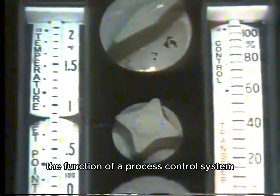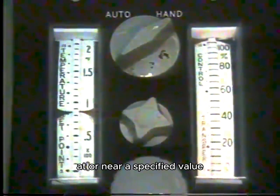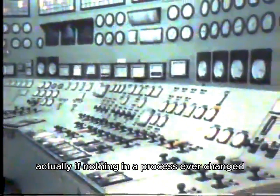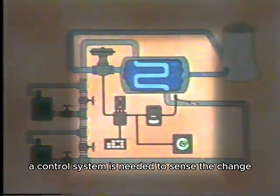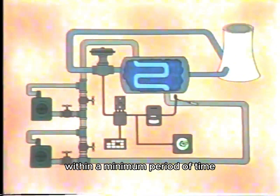But more specifically, when you hear someone talking about tuning a pneumatic control system, they're usually talking about adjusting a controller. The function of a process control system is to maintain a process variable at or near a specified value called set point. Actually, if nothing in a process ever changed, we wouldn't need a control system. But because processes do change, a control system is needed to sense the change and return the process to set point within a minimum period of time.